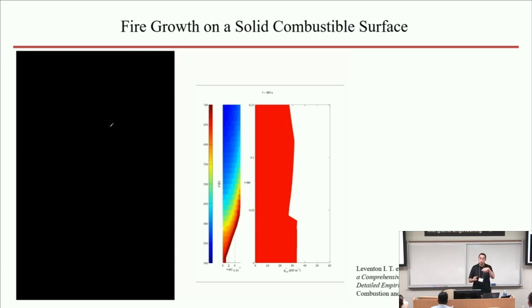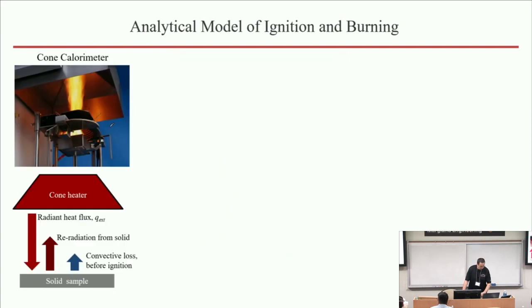And that process is going, and depending on the conditions, it can proceed in a steady form, it can accelerate or decelerate. And in this particular case, it accelerates because the heat feedback increases as the flame grows, which is ultimately driven by buoyancy. Right? So now we jump and talk about an analytical model that focuses on the solid portion of this flame.